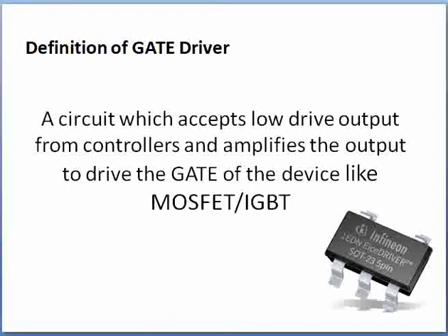It provides enough current to the gate of the MOSFETs we are talking about. This gate could be of a power MOSFET or an IGBT, which we find mainly in power conversion circuits, motor drive circuits, and predominantly in the electric vehicles we talk about these days. These gate drivers definitely play a significant role, and also in inverters and all these circuits.